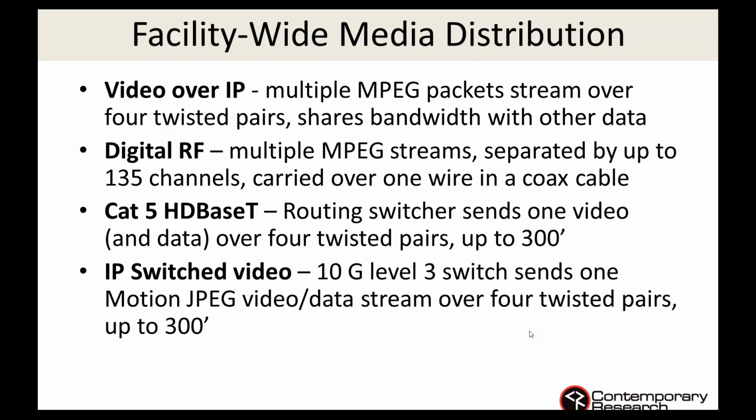You basically look at four concepts on distributing media over an entire facility. This is very different from trying to do this over conference rooms and boardrooms as we typically have done for media integration. The one people know the most or heard the most is video over IP or IPTV. And there you're sharing multiple MPEG packets streaming over 4 twisted pairs carrying Ethernet. And you're sharing the bandwidth of the streams with all the other data within the system.